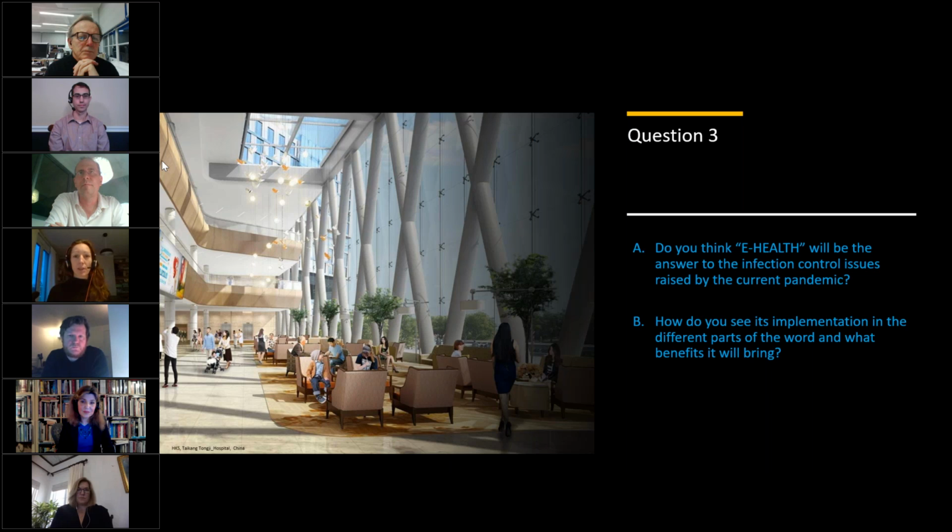So I can imagine that would be something that would be considered in the future. In any event, AGVs are becoming a more significant aspect of hospitals, and definitely for large hospitals, that has to be designed for, even if it's not being built in at the very beginning, but it has to be allowed for in the future so that it can be converted. So that would be in terms of vibration control on floors, flatness of floors, just allowing additional space in risers, etc., as I said before, so that you can actually then have AGVs in the future, if not now.